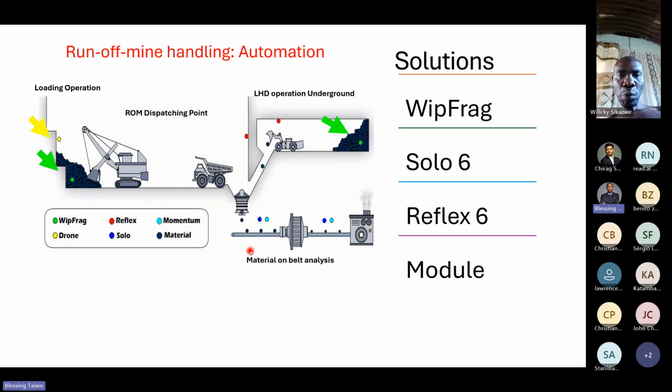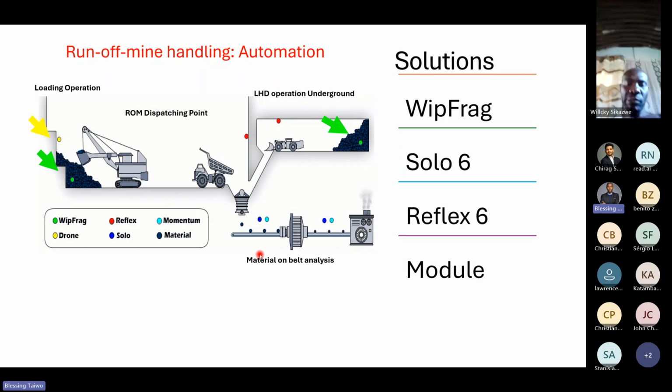This information will enhance your decision making: decision making about size reduction ratio, decision making about energy consumption of the crusher. If you are spending energy quantity X to reduce this material from this state to this state, then you want to compare the percentage of reduction that the crusher has done on this material. To have that in the early days, it always required stopping the belt and taking a belt cut.